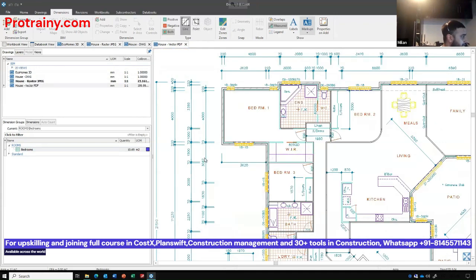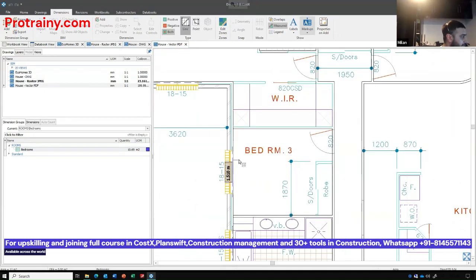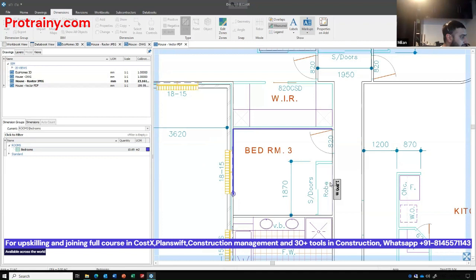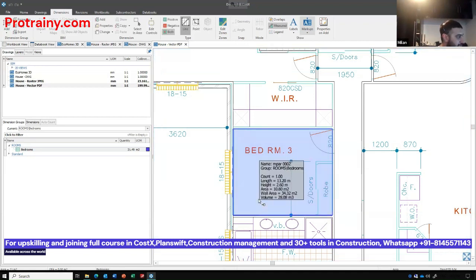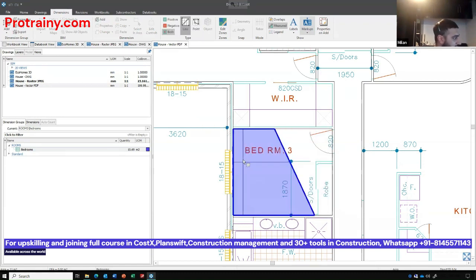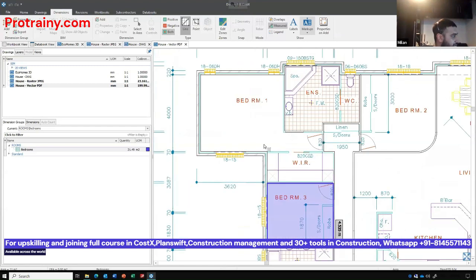And as we increase the intelligence and we go to the PDF, you can see now we're using lines. So now I can just click here, click each point, and I'm clicking lines. Notice that I have a wall area and a volume. So it gives me more than just area. So even though I have an area, also I have a length, which is the perimeter I can use for timber skirting, wall area I can use for painting, and volume I can also use for air conditioning. There's also other features like the shift key where I can measure any square area very quickly like this.